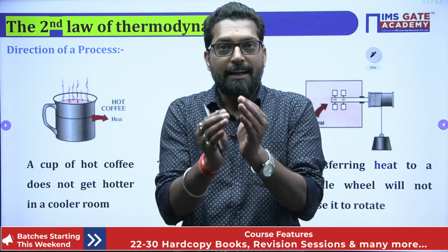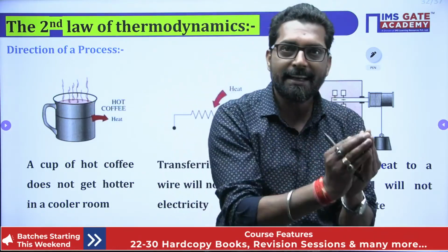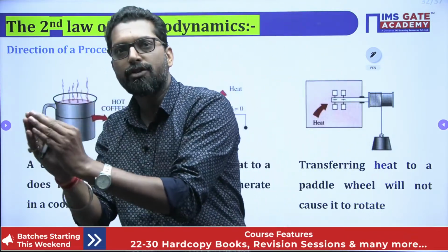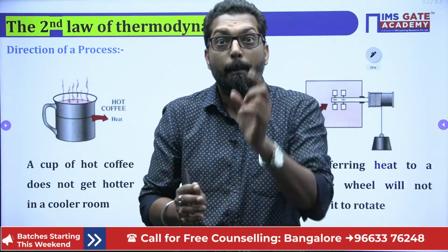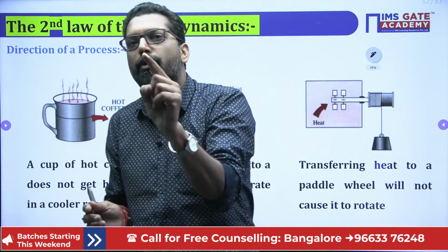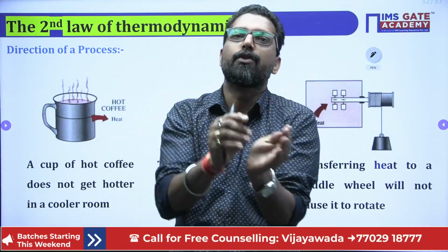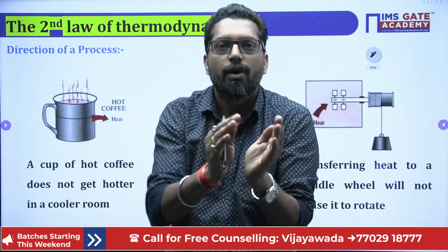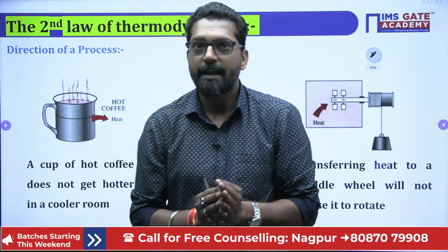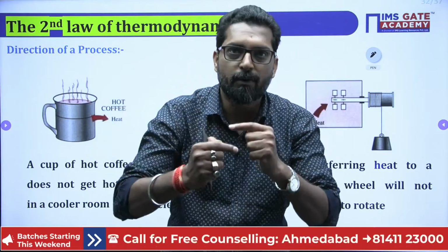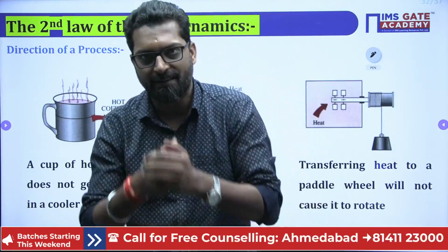Whether the fluid is at rest or in motion, the stored energy is there, right? But one extra component is added when the fluid flows, known as flow work, also known as pressure energy. That work is specific work, that is, work per unit mass.